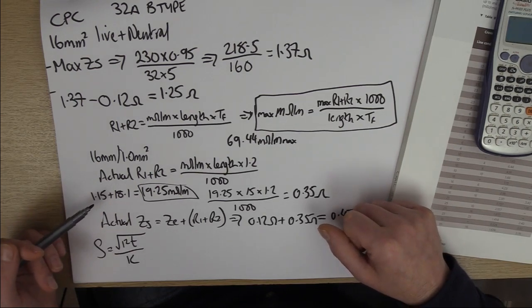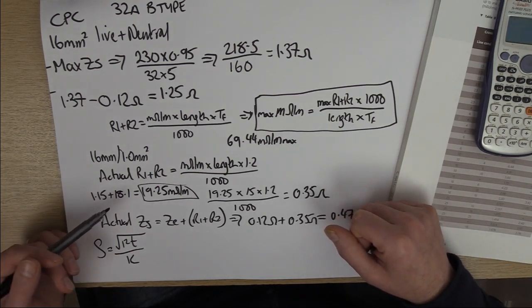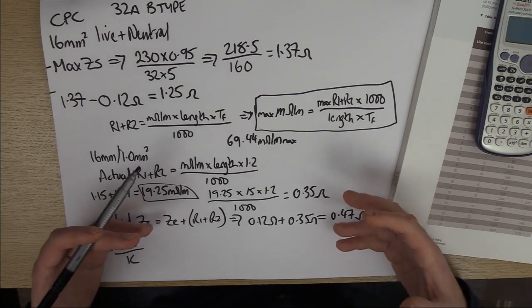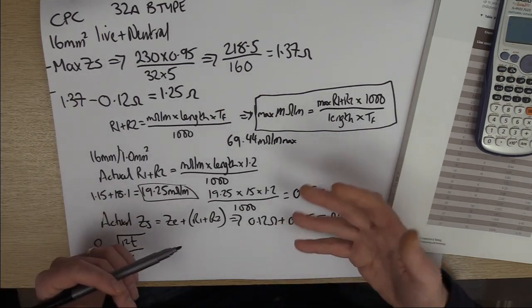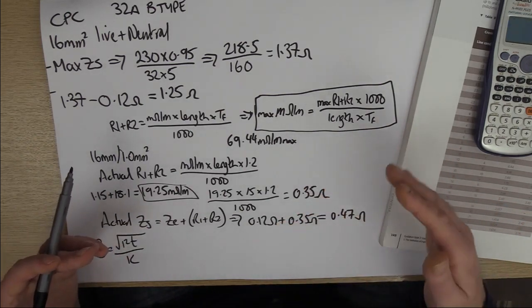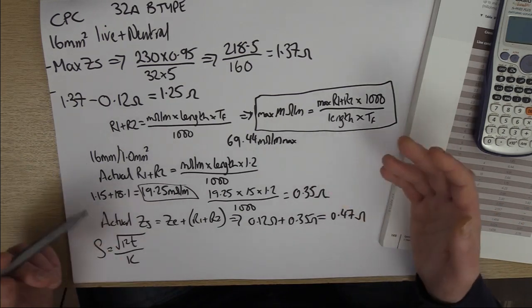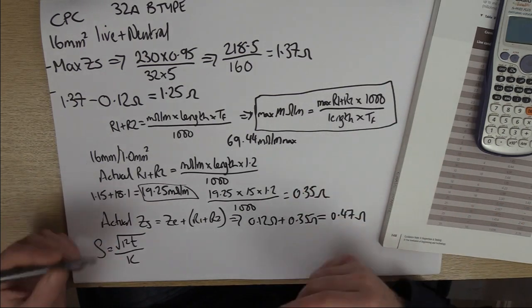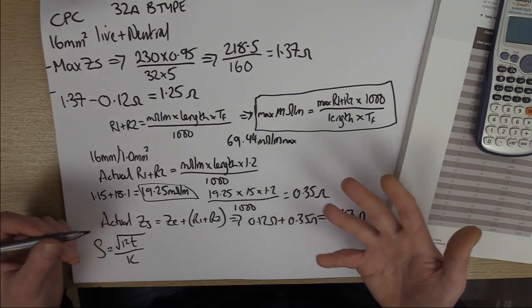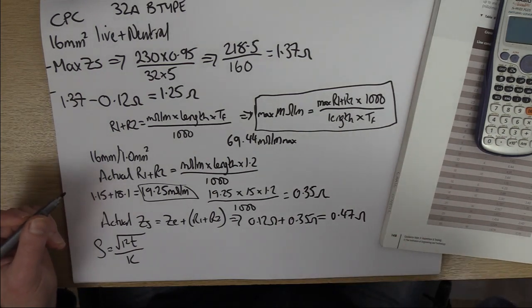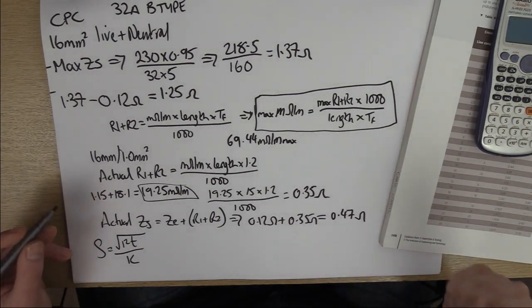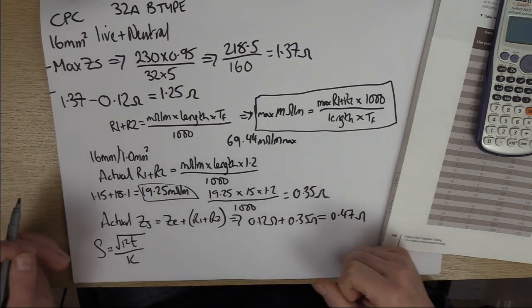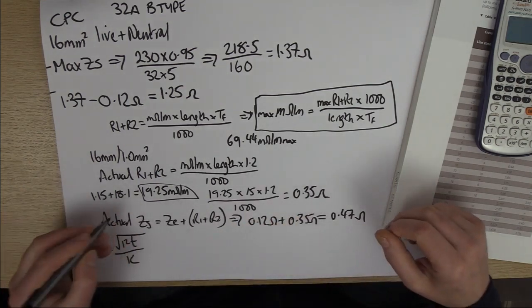The copper would probably survive. It's the insulation that we don't want to get damaged, because if it gets damaged, you can't trust it again, can you? So it needs to be within its kind of tolerances and safe limits. So we're not thinking the copper's going to melt here. I mean, it could in extreme cases, obviously, but what we're really seeing is about the insulation around it.